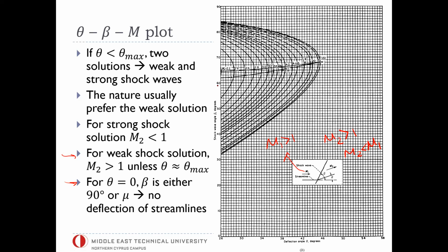down to the level of, I don't know, 0.3, 0.4, 0.5, something like that. So if the outside airflow is at Mach 2 and you need Mach 0.3 in front of your engine inside your aircraft, this basically means a significant level of deceleration. It's quite significant deceleration. And how do you decelerate? Of course, we use the physics of shock waves to do that, to decelerate the flow.